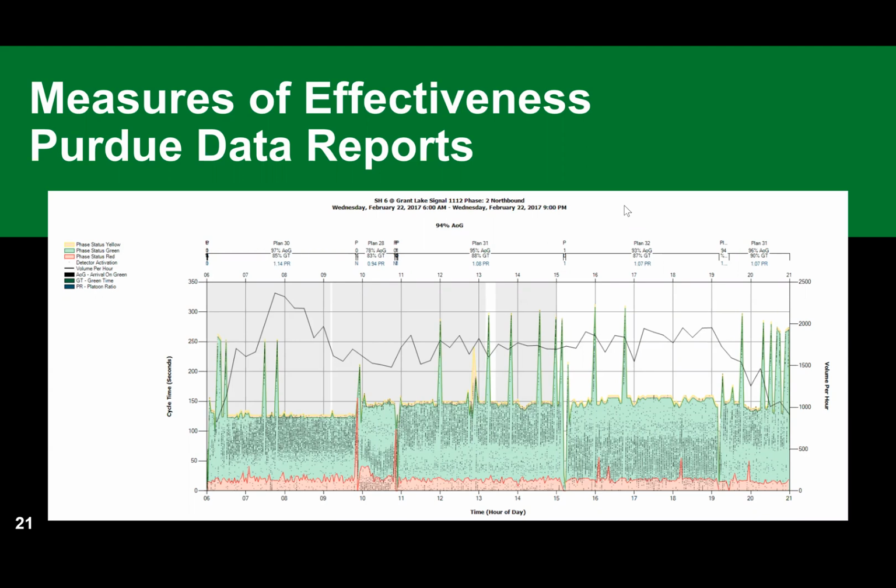Synchro requires a default saturation rate, and for SynchroGreen, is the road capacity saturation rate dynamic or predetermined? In regards to saturation, I don't believe it determines saturation, but I've never found an answer out there for saturation. I know what SynchroGreen can do is it can take you into saturation later, and it can bring you out of it sooner. So it can't fix saturation. Nothing can fix that, but more lanes, right? But there being a default as identifying saturation in Synchro, I don't believe there's actually a trigger for that.